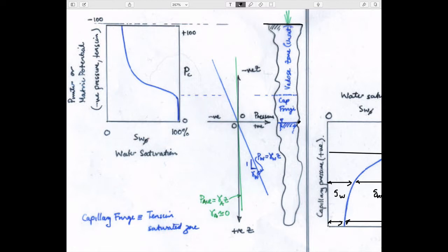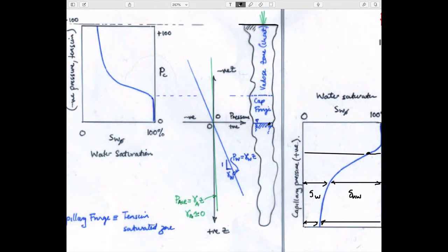The water table is still here at the same level at the bottom. Probably in 452 you talked about the vadose zone and the capillary saturated zone. In other words, the zone that is saturated because the surface tension in the water is high enough to pull up the water, just like in a capillary tube. This actual location here is at atmospheric pressure, and this pressure here is less than atmospheric pressure because of the capillary fringe. And above this, it's basically air.